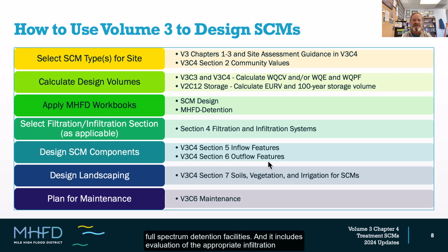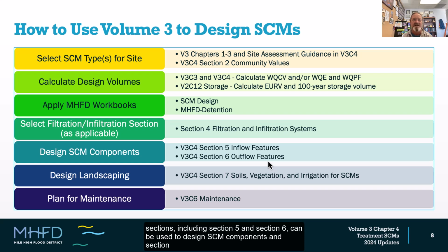spectrum detention facilities. And it includes evaluation of the appropriate infiltration or filtration section to be used if you're able to use a filtration or infiltration-based BMP. Several sections of Chapter 4 in the front sections, including Section 5 and Section 6, can be used to design SCM components, and Section 7 of Chapter 4 can be used to provide guidance and information on soils, vegetation, and irrigation. And of course, no design of an SCM is complete without maintenance considerations, and maintenance is addressed in Chapter 6 of Volume 3.